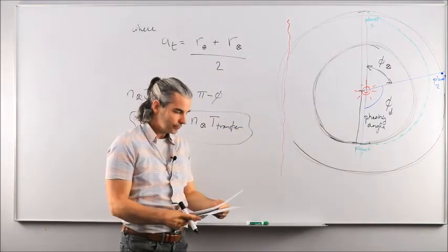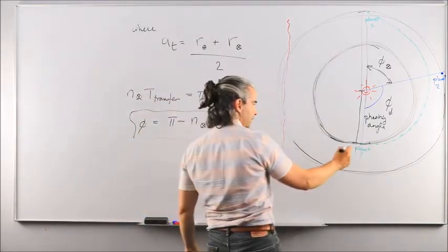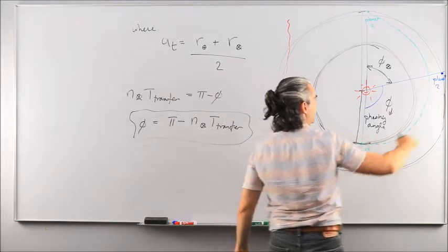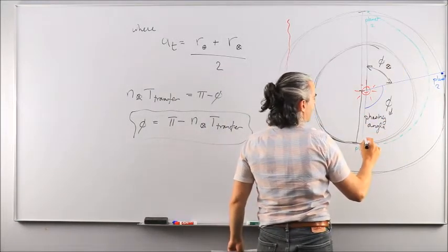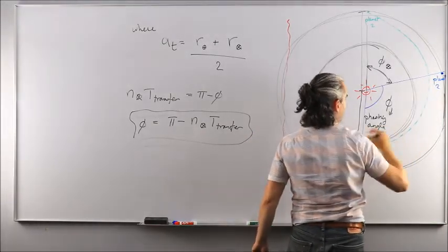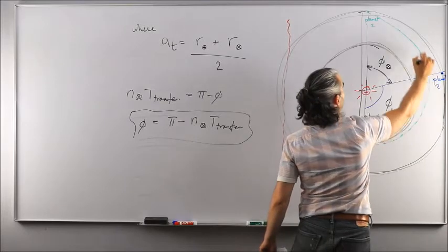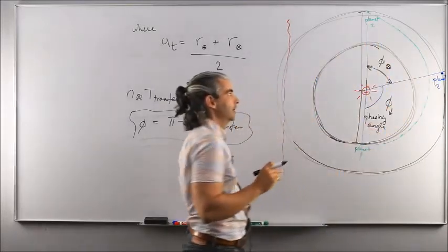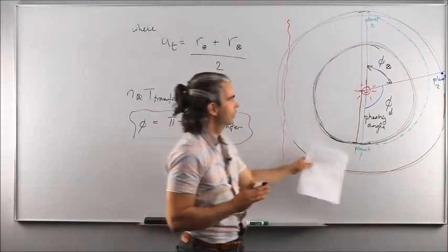Okay? And that is assuming that all you do is one delta V maneuver here, kick yourself onto the hyperbolic departure orbit that will then freely drift you onto this elliptical transfer orbit and then eventually reach planet 2 without any other delta V maneuvers throughout the way.